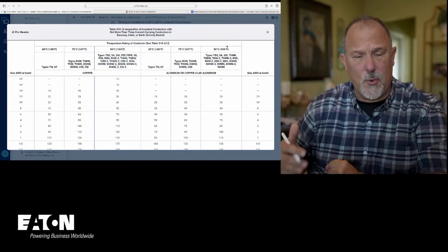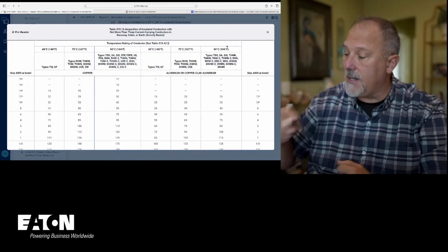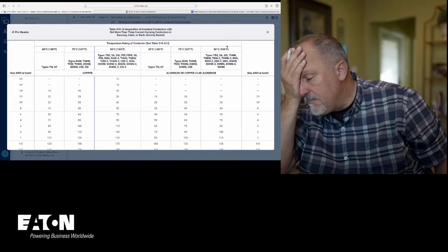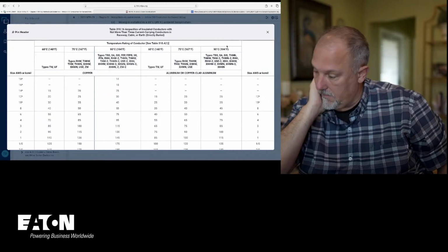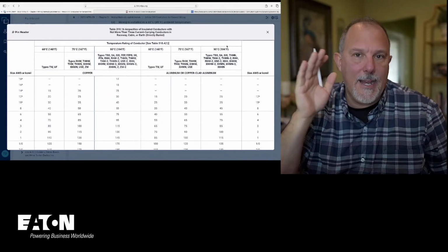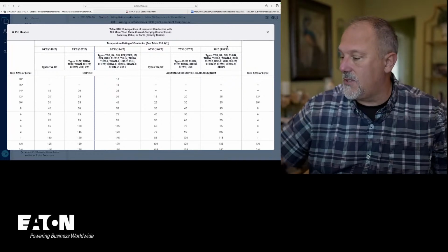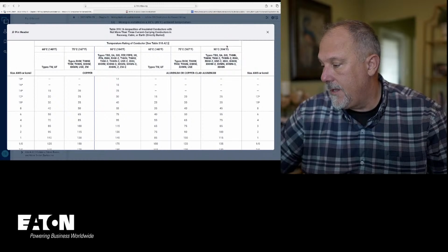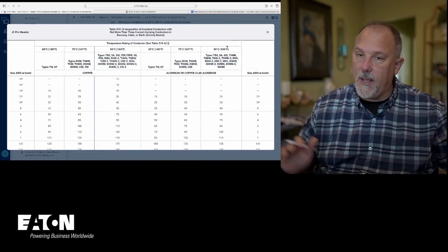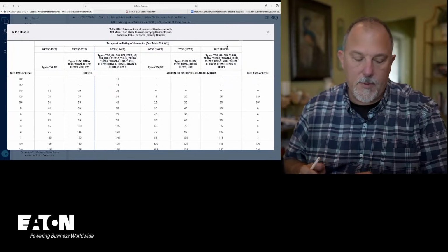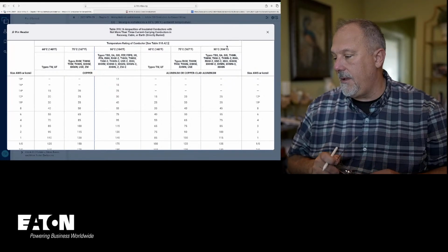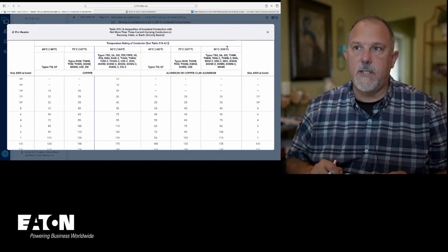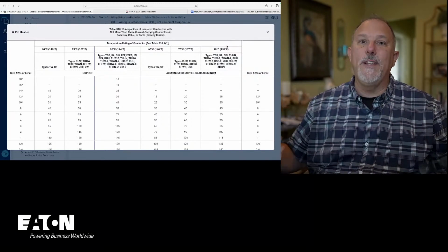So what I've got to do is make sure that my conductor has at least 800 amps, and it's non-continuous. So I got to remember, this is non-continuous. And I had this discussion, and I know I had some people disagree with me, and one individual came up to me and said, hey, Tom, I think it's a continuous load, because transformers are always on.